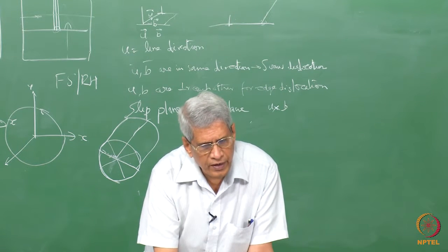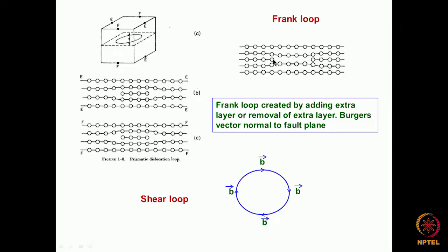If they agglomerate together on a particular plane, this is the sort of structure that will be formed, because one set of atoms is missing, which is equivalent to the point defects which are generated. This is only a cross section which we are showing. If you look at it everywhere, there is one extra plane on this side of it, and in between there is nothing. This is a three-dimensional view of it.